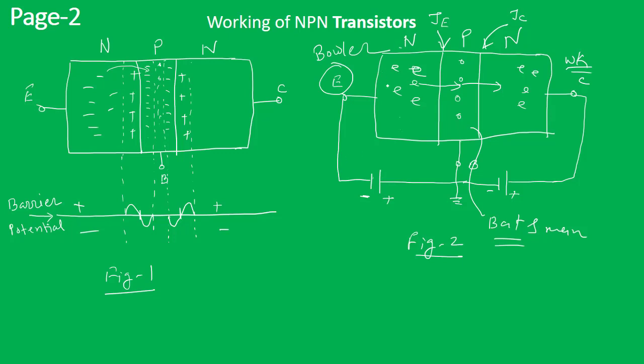The emitter is the bowler, and the base is the batsman who is connecting very few balls or playing very few shots, as it is a test match. As a result, we have less recombination, and the majority of the electrons pass through the base, because it is very thin as well as very lightly doped. So most of the electrons pass from the emitter to the collector, and the collector is collecting them.